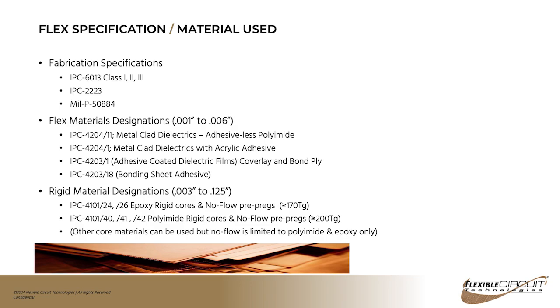The materials on your flexible circuit drawing should be called out per the IPC specifications 4202, 4203, and 4204. And like I said, by referencing those on your flexible circuit drawing, you'll make sure that you get the right stack up.